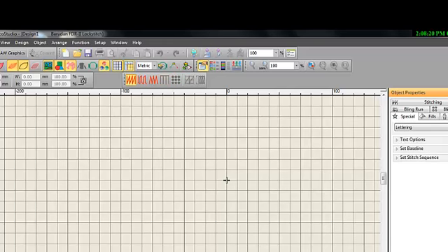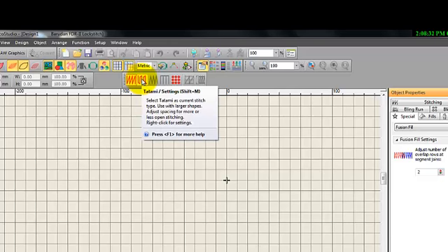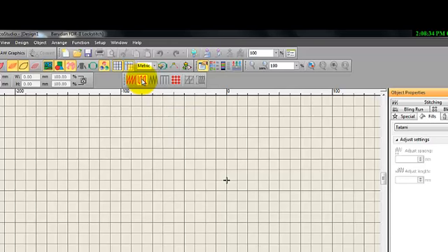and your font tool. Okay, so let's start at the top of the list with our Fusion fill, and I'm going to create a larger shaped object. So I'm going to select tatami stitch. Now I can right click on that to bring its values up. And there it is, tatami.